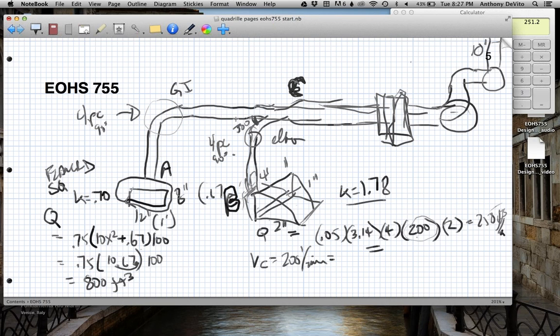So the distance from A to C in terms of the amount of ductwork, I'm going to say that that's 50 feet of ductwork. The distance between, and there's one elbow, the distance between this slot hood and the junction, I'm going to say is shorter, it's 30 feet. Okay, it's also galvanized iron. It's 30 feet and it's a 30-degree angle on the junction. And then the distance from C to the fan, I'm going to call the fan D, it's going to be another 50 feet.